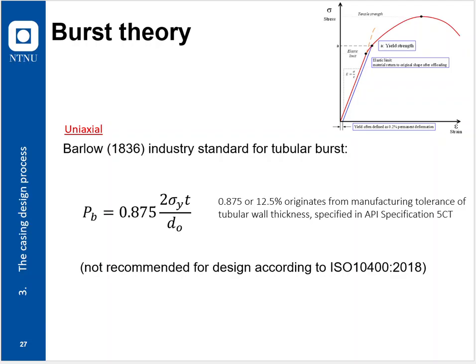To put even more understanding to why this formula is a little bit out of place, it has this factor 0.875, or it relates to 12.5%. You just remove 12.5% of what the burst is giving you. Taking away this one means you have the full burst ratio of the pipe, whereas adding it removes 12.5%. You get that. It's very simple, very mathematically easy to see.